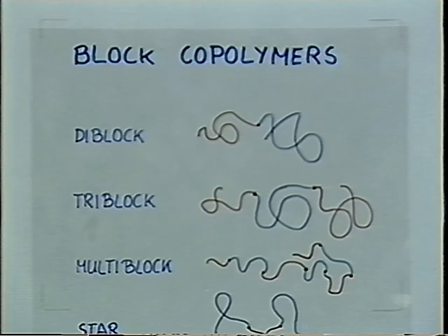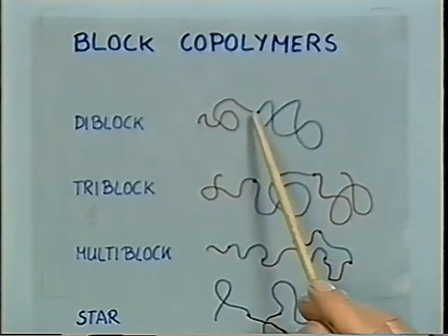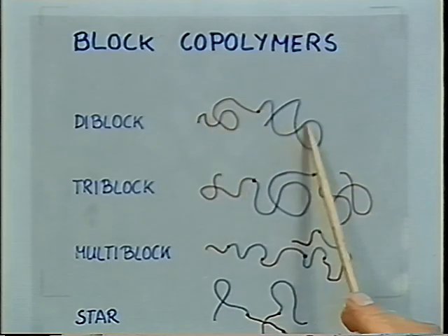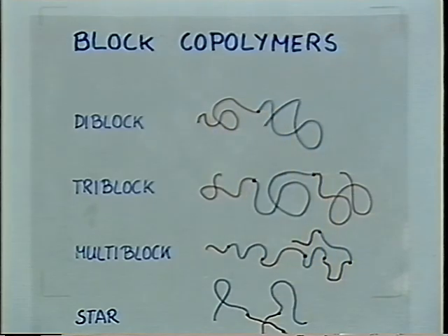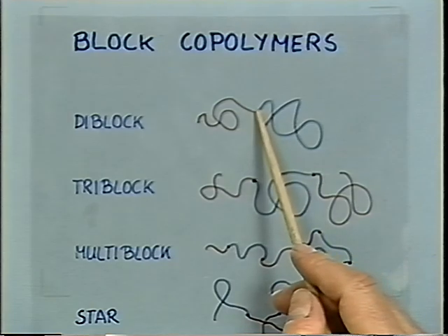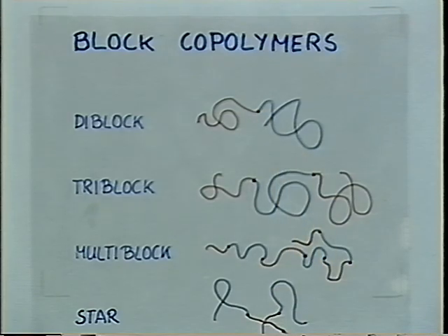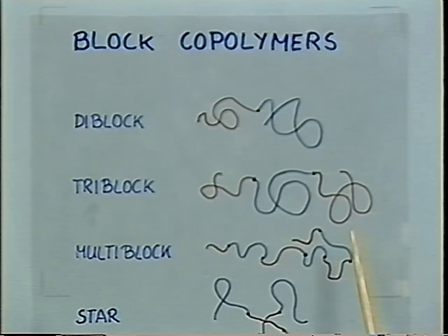Chemists are able to link immiscible blocks, that would be one block, with another immiscible block, and they would naturally not mix on a molecular level, but since they are tied with a chemical bond, they cannot separate beyond molecular level. So we will get phase morphology on the 100 angstrom level, on the radius of gyration level of those molecules.